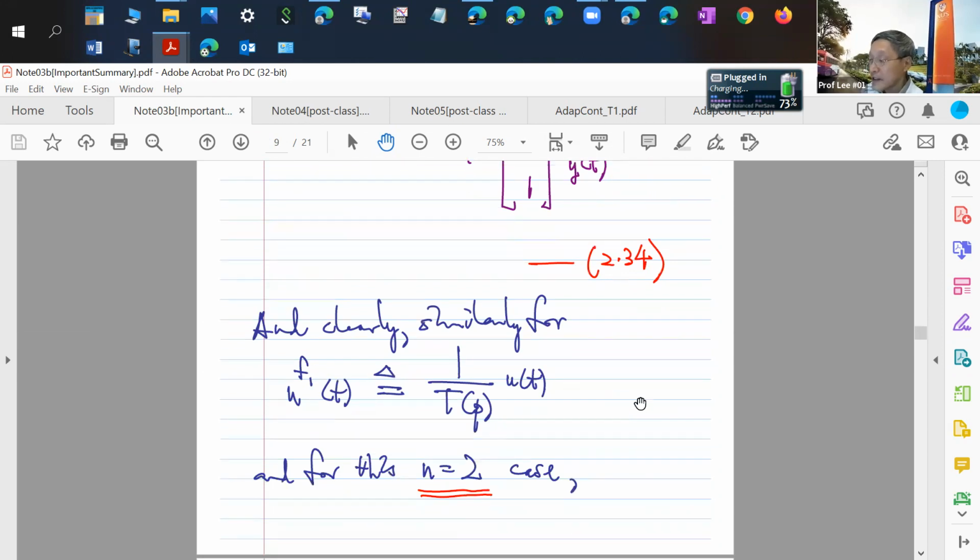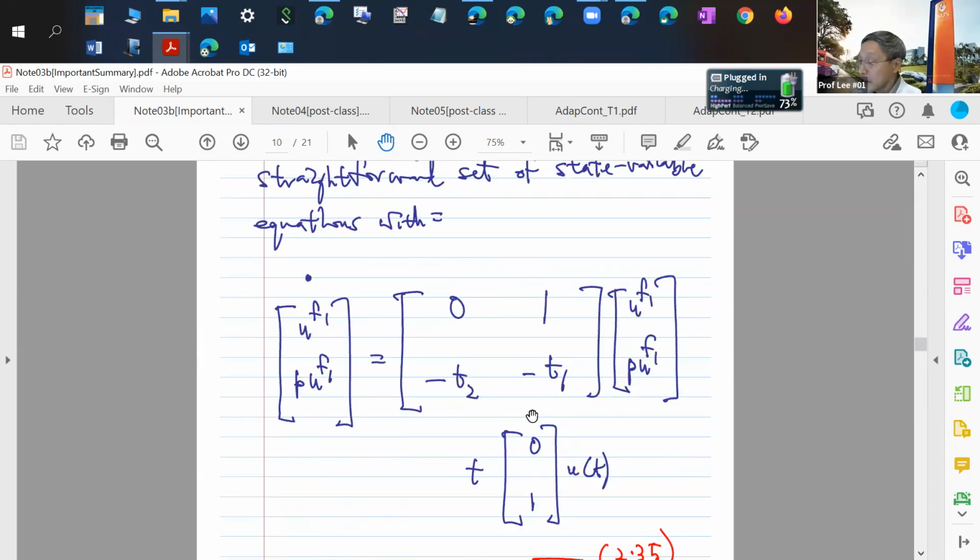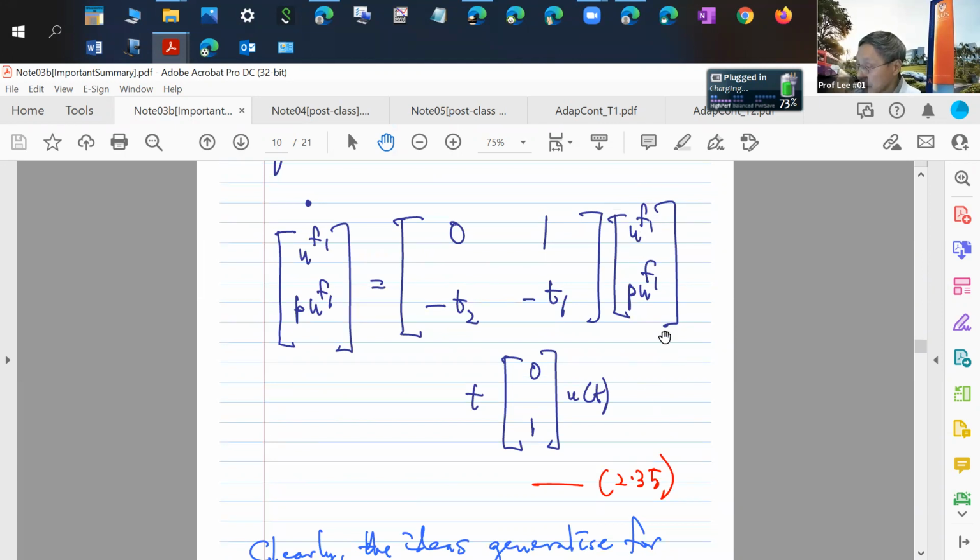Similarly, you told me U is also measurable. That makes sense because you are the person generating U. So you can take U and similarly pass it through a 1/T filter with the same kind of constraints. The only thing needed is that T needs to be stable and of order n, and it's exactly the same T. So you take U, pass it through the 1/T filter, and again set it up in controller canonical form. You get these two signals coming out.